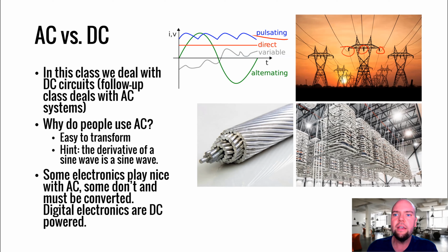They're big steel towers, and the reason they're big and they use a lot of steel and they're not cheap to build these towers is because you have to keep these conductors not only far away from each other but far away from people who could be walking nearby, and you probably don't want to get anywhere near a 1,000,000 volt conductor that's just out exposed to the air. So that's the downside of high voltage: it's dangerous and you have to keep the conductors far apart from each other. But the flip side is it allows us to relatively inexpensively send a lot of power a long distance. Although that's not a feature of AC versus DC.